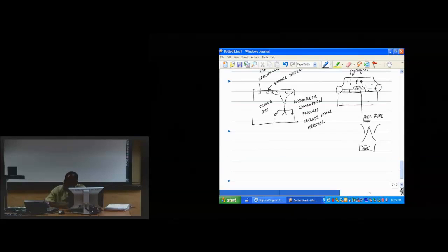So it's much easier for a flame to spread at an inclined angle. If we have this flame spread process, this is a lot easier because we're getting a flow associated with buoyancy that's pulling the flame and helping in terms of the spread process.